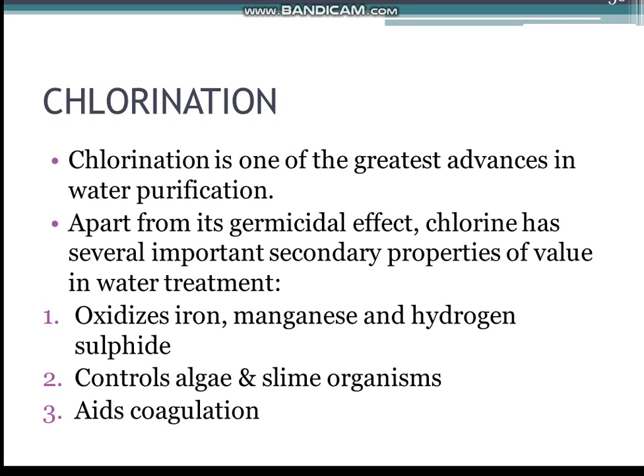Chlorination. Chlorination is one of the greatest advances in water purification. It is a supplement, not a substitute to sand filtration. Chlorine kills pathogenic bacteria, but it has no effect on spores and certain viruses, except in high doses. Apart from its germicidal effect, chlorine has several important secondary properties of value in water treatment. It oxidizes iron, manganese, and hydrogen sulfide. It destroys some taste and odor producing constituents. It controls algae and slime organisms and aids coagulation.